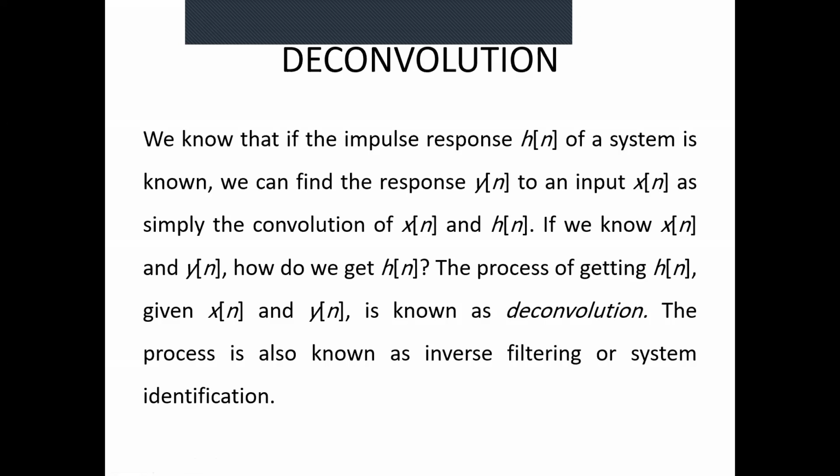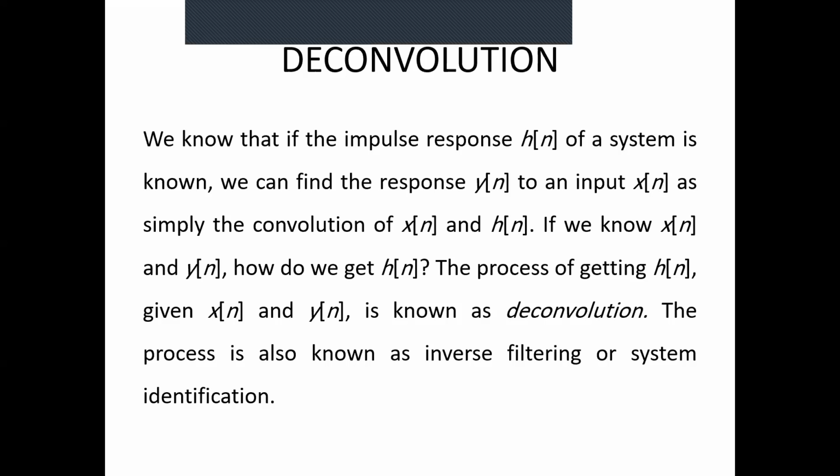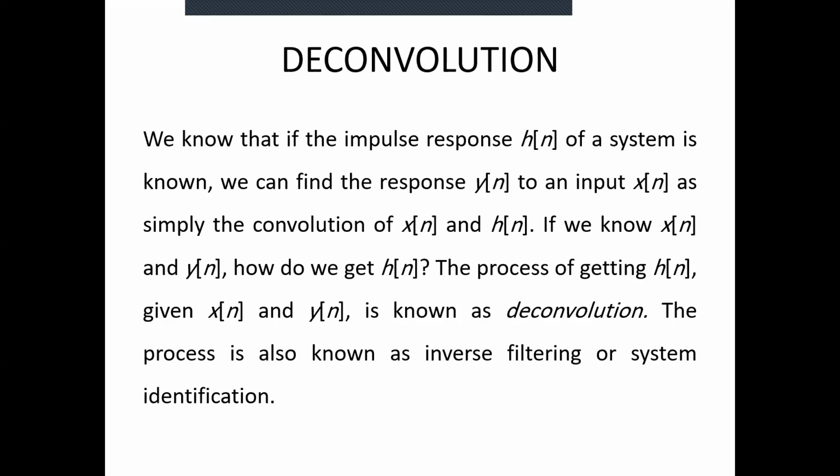Now, practically, we have some cases. For example, the system impulse response is unknown, okay? So how are we going to measure the impulse response of the system? For example, you are given a black box, and you are asked to determine the impulse response for this black box. What you are going to do is feed the input of this black box with an input x, and measure the output.